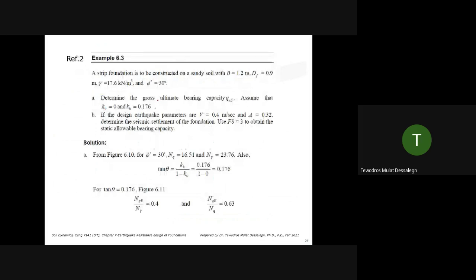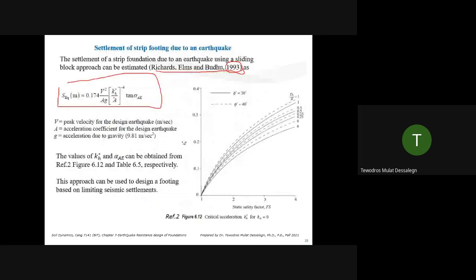And so you can get the settlement. This is just an approximate, empirical equation if you have to use it. It doesn't mean that it's widely used right now. In US, I never use this equation. We usually use software nowadays because we have better tools and they are available. So we estimate settlements using Plaxis. You can model it in Plaxis and see what the settlement is.